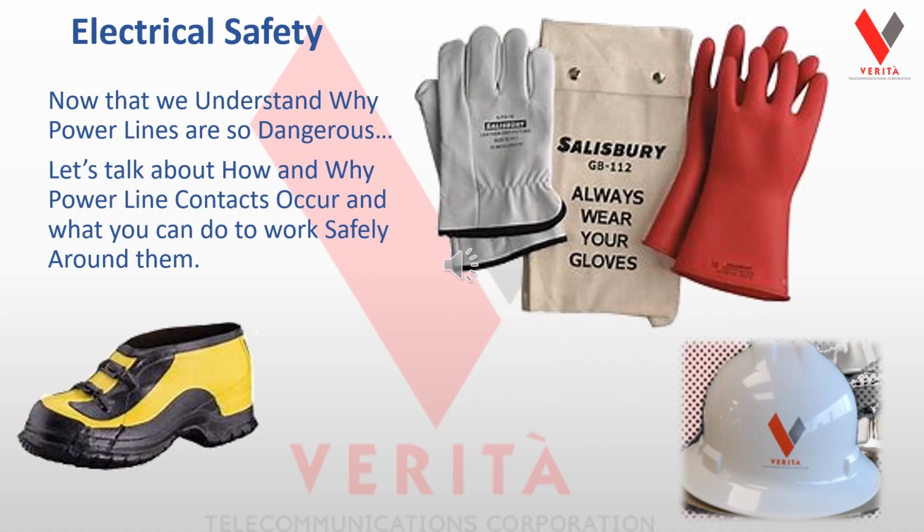Now that we understand why power lines are so dangerous, let's talk about how and why power line contacts occur and what we can do to work safely around them. You see here we have our safety gear, our hot gloves with our overglove protectors, and our hard hat. Both these pieces of equipment are rated for 17,000 volts of AC. And also for the underground folks, the locators, the tracers, trackers, and operators, we have dielectric boots to help protect them.